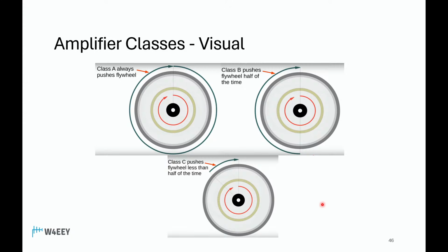All right, now I'll start connecting this to some things we've talked about in the past. Now the RF output circuits that we looked at before, the tank circuits, remember there was a coil and capacitor in parallel, and if we tap that circuit just for a little bit, it starts ringing at the resonant frequency, and it'll keep ringing even when we take the input signal away. So we can kind of see that working its way out here.